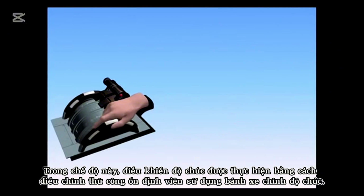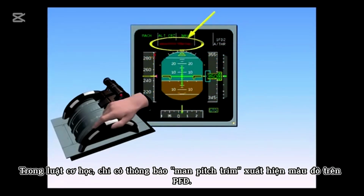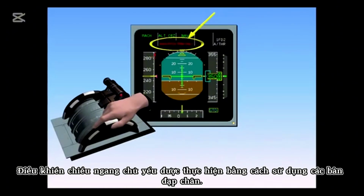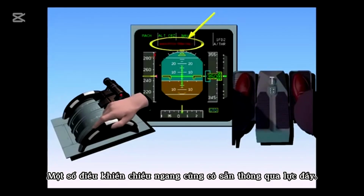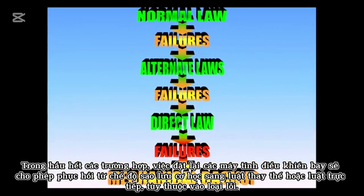In this mode, pitch control is accomplished by manually trimming the stabilizer by using the pitch trim wheel. Some pitch control can also be gained by use of thrust. In mechanical law, man pitch trim only appears in red on the PFD. Lateral control is achieved primarily by using the rudder pedals. Some lateral control is also available through thrust. In most cases, resetting the flight control computers will allow recovery from mechanical backup to either alternate or direct law, depending on the type of failure.